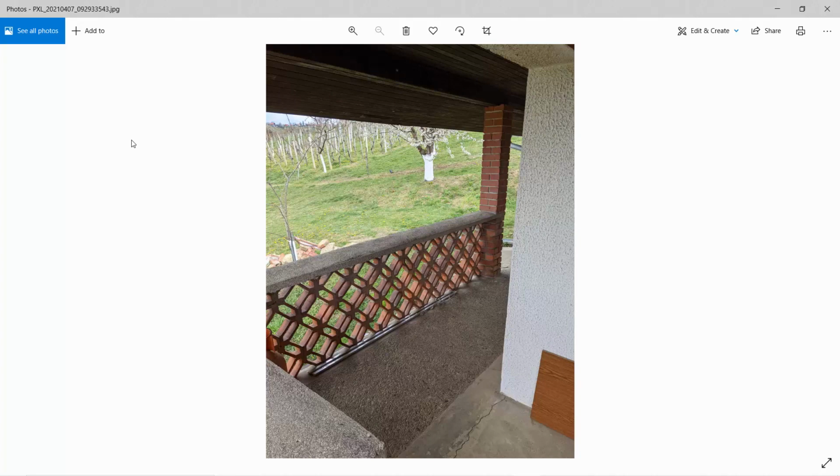So the first and most important point is that you try to get similar perspectives with a drone and with a phone. At least, let's say, 5 images which need to be from the same distance from the object, at pretty much the same height and same scale, and then you're able to successfully match all the images in your bundle adjustment step. Of course, if you fly with the drone at 5 meters and you trigger with the camera at 2 meters height, this will also be okay.